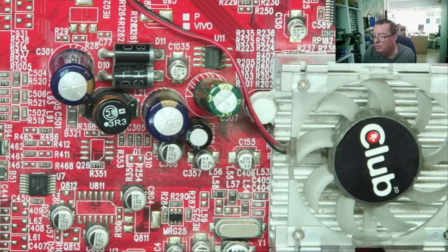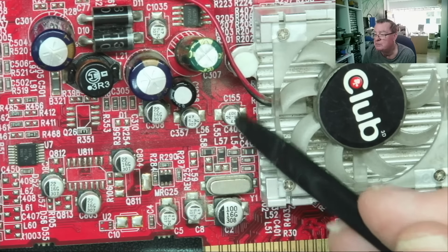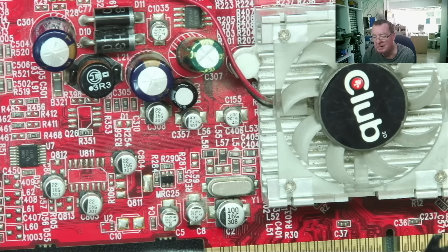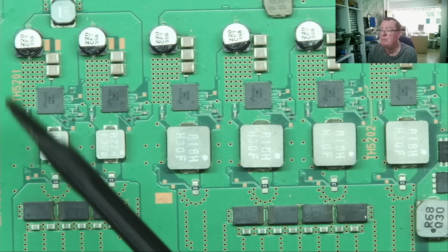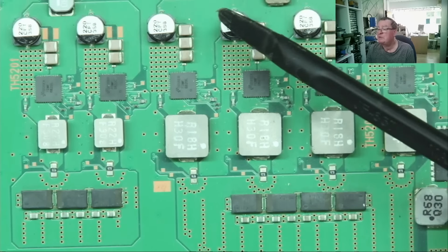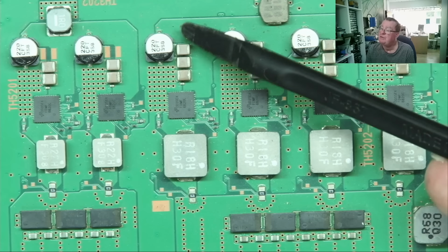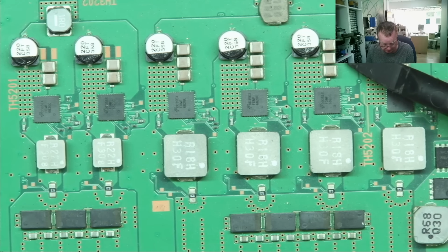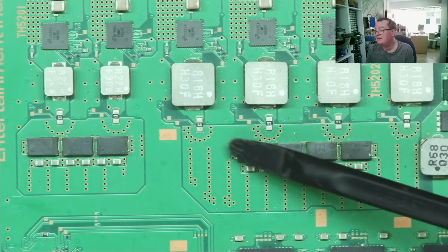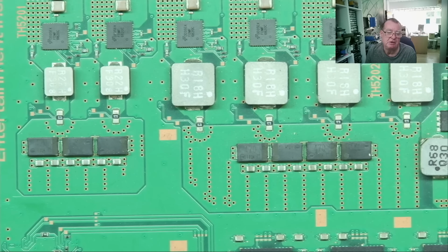Other types of what you may consider to be electrolytic capacitors, which are these ones, are solid electrolytic or polymer capacitors. These are not prone to failing in the same way. Again, we see more of them here. This is a VRM or voltage regulator module with multiple phases firing in sequence, like a Gatling gun basically. These capacitors are less prone to failure. And specifically on this one, these are on the input of the circuit, so they are not subjected to the high frequency noise. The output capacitors in this one are these tantalum. These don't tend to fail, and certainly not in the same way.